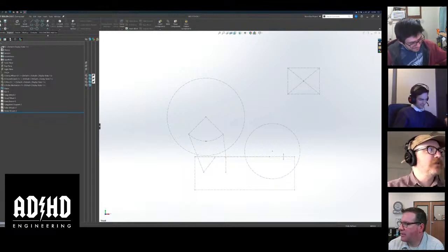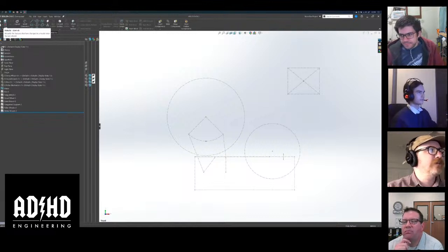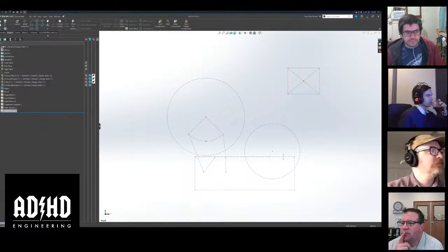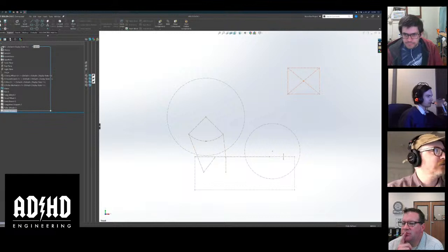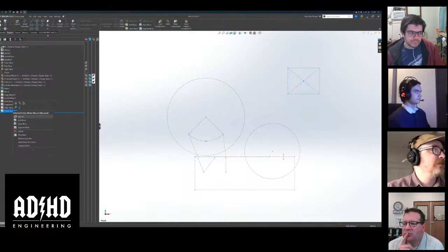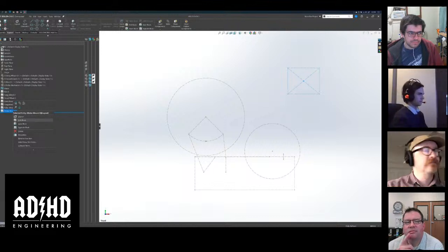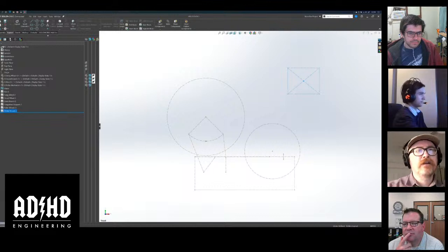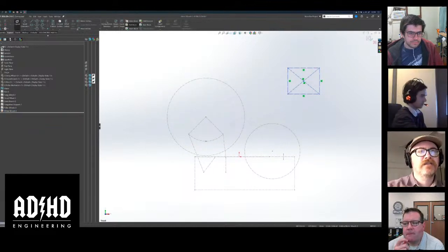Okay, so we created the block. I did a rebuild. Probably didn't need to do that. It was prompting me to, so I did. But anyway, that closed the sketch like it would always. But now I can actually go back into my layout, even from there. And we don't want to edit the... I'm sorry, take that back. We need to edit the block now because remember, it doesn't have any defined geometry. So now here's our block.